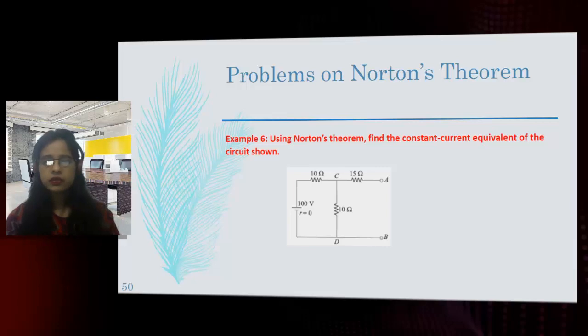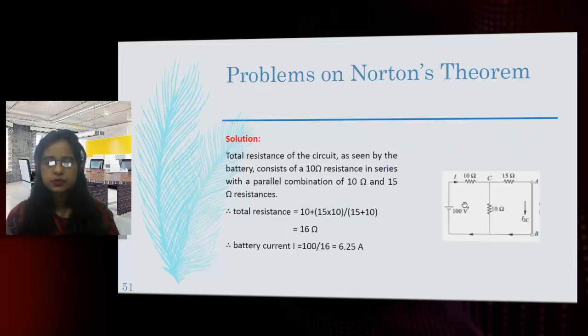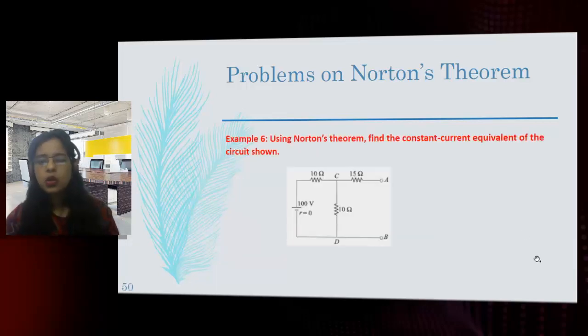Again the equivalent circuit will be found out. So what is the first step? First step is always to remove the load. Now here there is no load again, this terminal is open, right? Then we'll short the open terminals. So we'll directly short this terminal. Okay, we'll directly short this terminal. What will happen then? If you directly short, this circuit is completed, right?